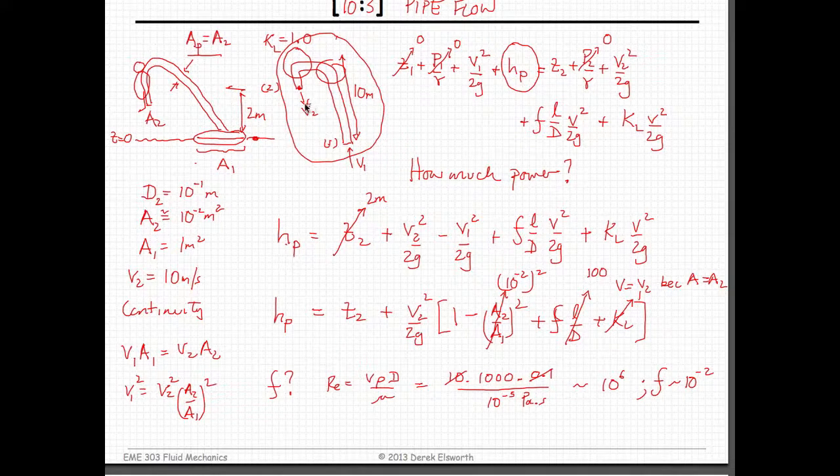So as a matter of defining this velocity, we know what the Reynolds number is within the pipe, and so directly, if we know the Reynolds number, we can figure out what the friction factor is. But if you think about the behavior being defined in terms of upstream and downstream pressures, where we have to solve for the velocities, then we have to iterate on the Reynolds number and therefore iterate on a friction factor.